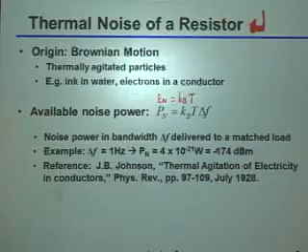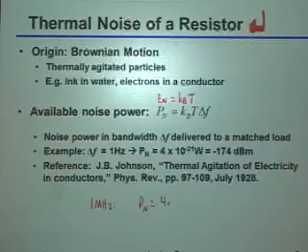It's quite useful. Just to make sure people are still awake and paying attention, if I had a 1 megahertz bandwidth, what would my noise power be? Oh, okay, you did it in dBm. Let's actually do it in absolute terms, because that's hopefully more obvious for most people. The answer you gave was correct, but yes, exactly, it's going to be 4 e minus 15 watts, or 4 femtowatts.